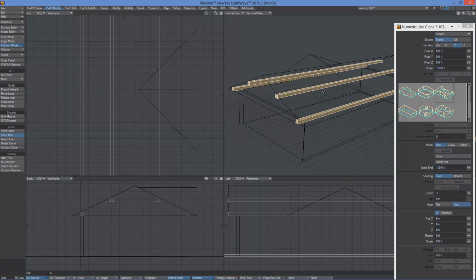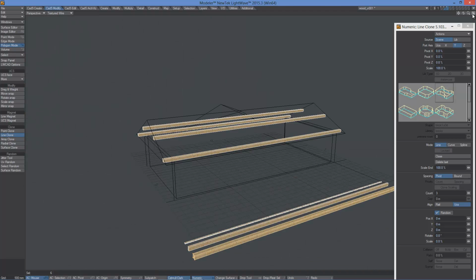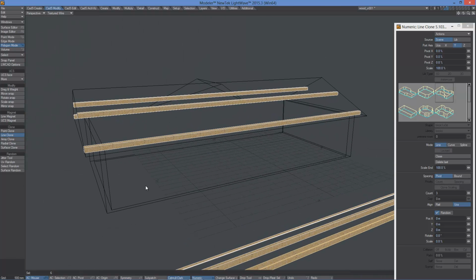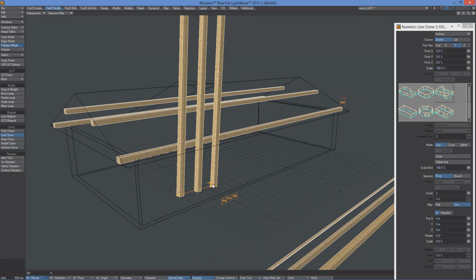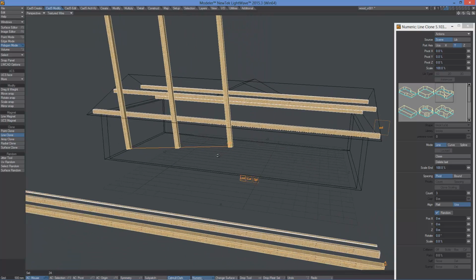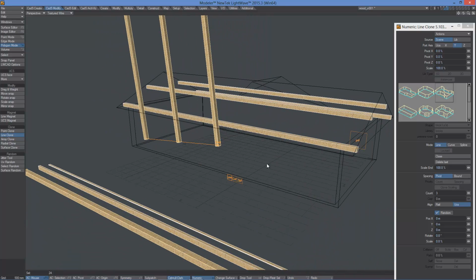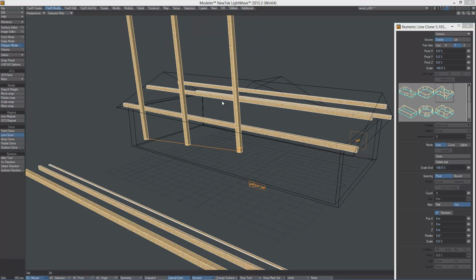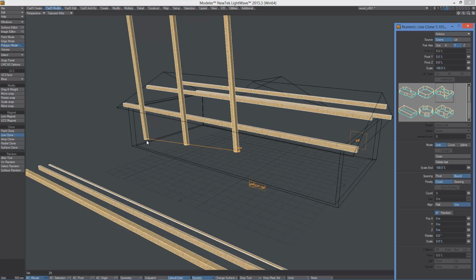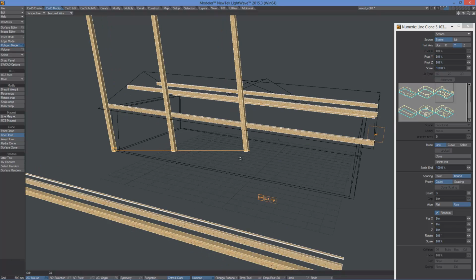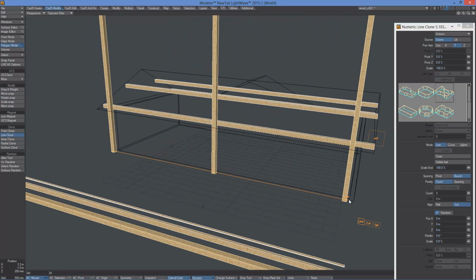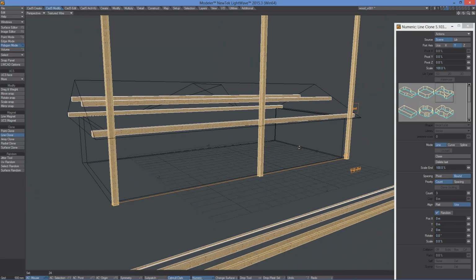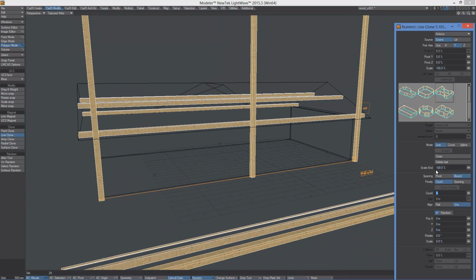So when I click on this wall here in the perspective viewport, the first click defines an automatic UCS lying on this wall, and the final placement of the cloning is now on this wall. We set cloning spacing from pivot to bound and set line cloning from one corner of the wall to another, and we set the count to 7.